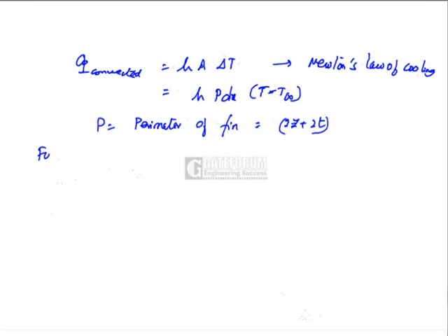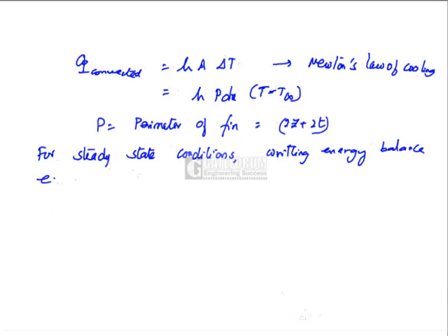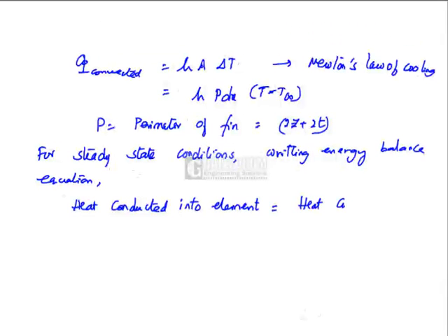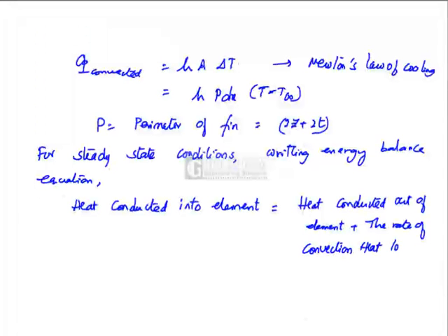So, for steady state conditions, writing energy balance equation, that is heat conducted into element should be equal to heat conducted out of element plus the rate of convection heat loss from element to fluid.